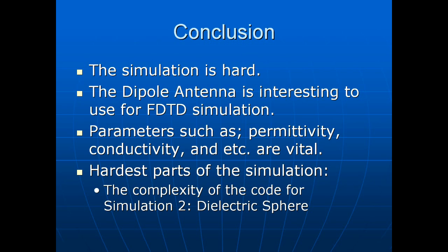The other thing I learned a lot about was the dipole antenna and how it's used for the FDTD simulation. I learned a lot about what it's used for, and how it's reflected in the design parameters, such as beam width, gain, and directivity, because those are really important design parameters that any analyst can calculate when it comes to advanced electromagnetics, or even in the workforce. Those are things you would normally want to calculate or solve out as far as your design goes.